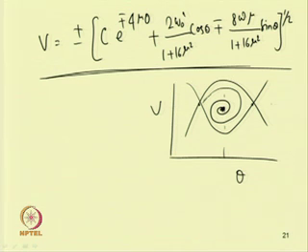Similarly, here one can have a saddle. For different initial conditions, it will come to the equilibrium position, or it becomes 0 0. So this will be 0 0 corresponding to this, and it becomes a stable focus. So instead of a stable node, as in case of the conservative system, that is without considering damping, in this case one has a stable focus.